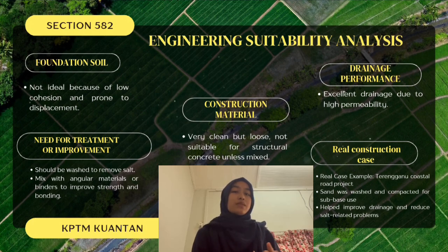As a construction material, it is very clean but loose. The particles don't bind well, so it's not suitable for structural concrete unless it is mixed with angular sand. In terms of drainage performance, beach sand performs very well. Its high permeability allows water to pass through quickly, which helps reduce water buildup.